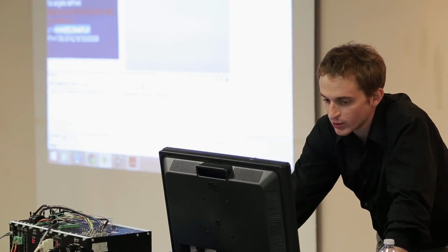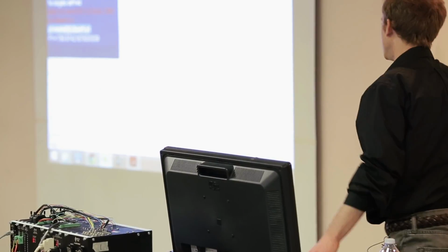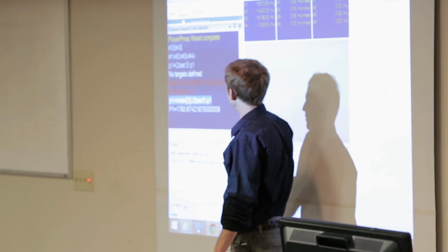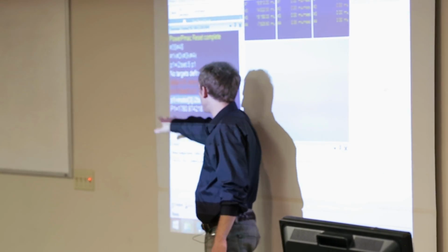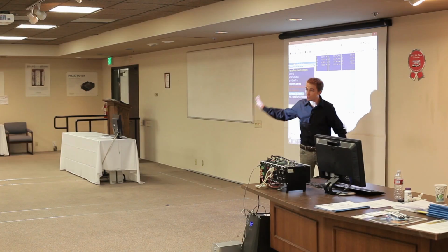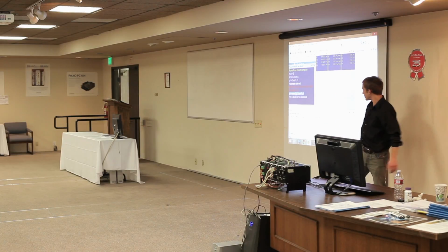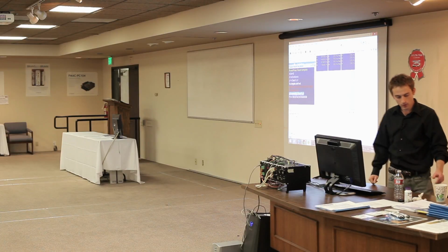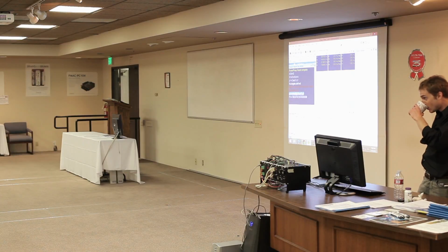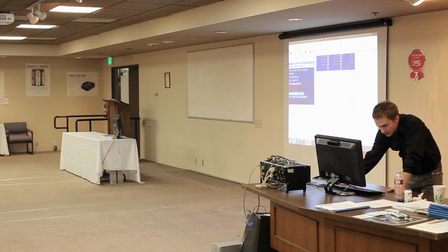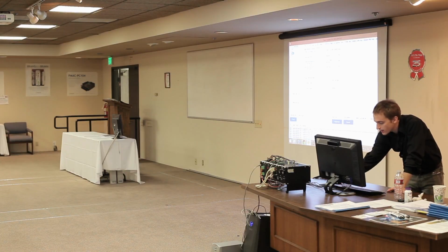And I got that just by computing it in the terminal window. You can do the same thing I did if you want. It's just a handy trick. You write something like P1 equals motor3.I2T set over 5, P1. It will compute this value, stuff it into a variable, and then display the variable. You haven't learned what a P variable is yet, so don't worry too much about that. It's just a general purpose variable you can use for calculations. So then I take that result, 1780, and stuff it in my step magnitude and then issue the current loop step.